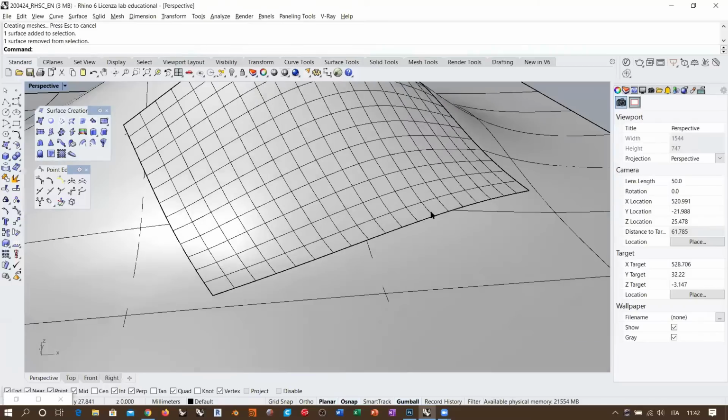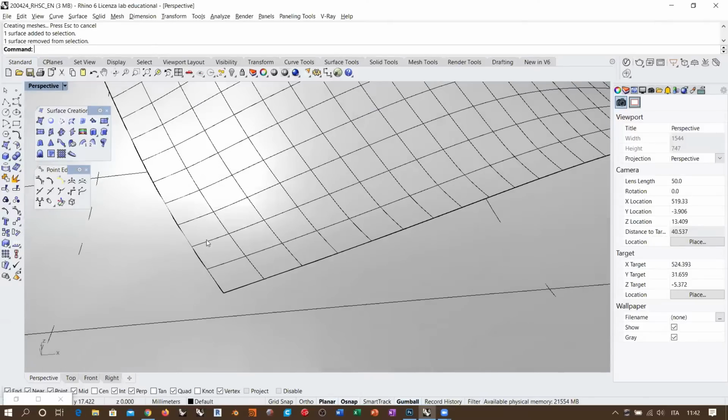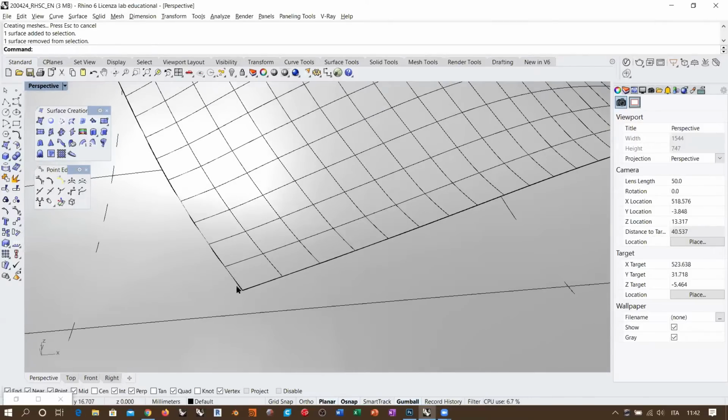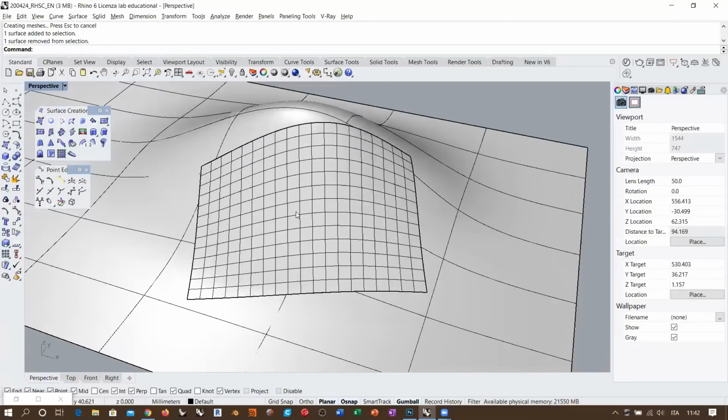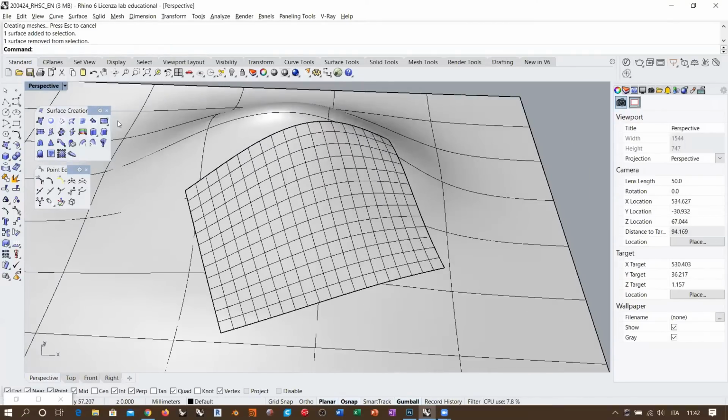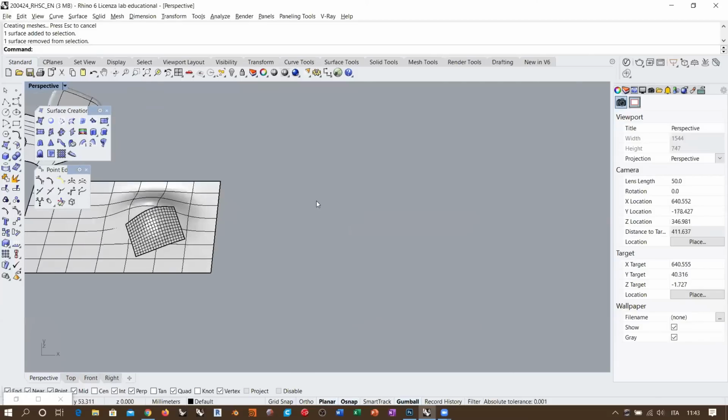But this is something that can easily be achieved along the edges, but in the end, this surface must touch this corner and must turn around the corner with this orientation that depends on this other edge. So basically, if this other edge is not curvature continuous with, for example, the corresponding extension along the surface, the surface cannot be curvature continuous in the corner. So this is the first problem that you get when you try to adjust things with network surface. I can show you this with another example in order to exaggerate a little, but this will make things a little more clear.